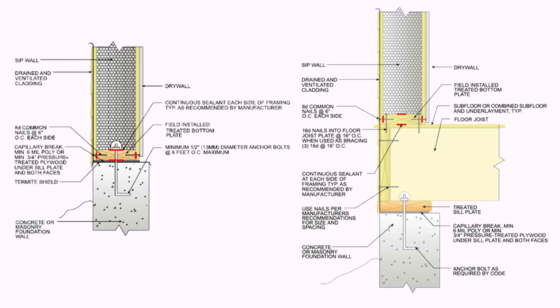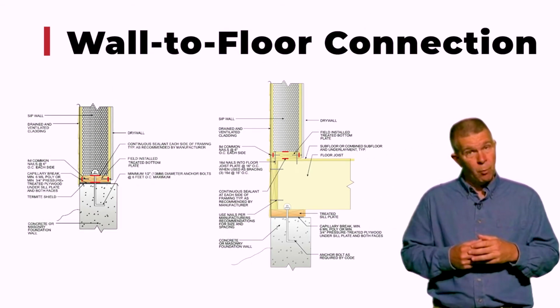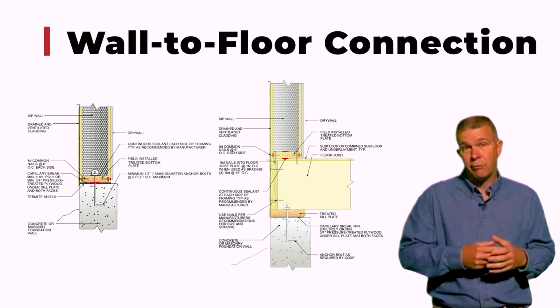But of course, you've got the consideration of the foundation being wide enough to bear both the floor system as well as the wall system. In the middle, you can see that typical platform frame system where you have a floor built first and the wall panel goes on top of it. Again, here we have to go back in and insulate that floor system.